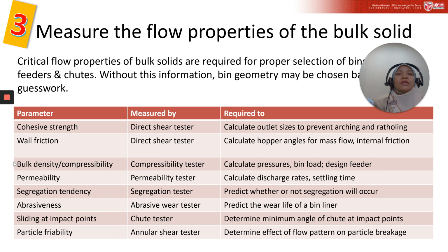different powder, even though it has a similar chemical content, will not give the same flow properties. So remember, the real practice is for you to get some sample of the bulk solid first, and then do the test before you design the equipment, in order for you to understand the behavior of the bulk solid.